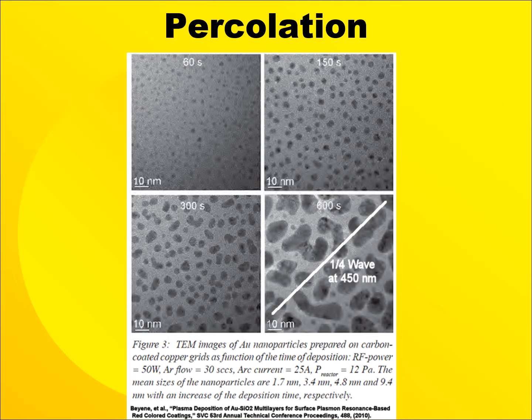The typical deposition of a metal layer on a nanoscale looks like falling rain, produces little islands, and they get bigger with the nucleation of additional material, and they start to touch each other and coalesce or percolate as they get bigger and bigger till they finally form a continuous film.